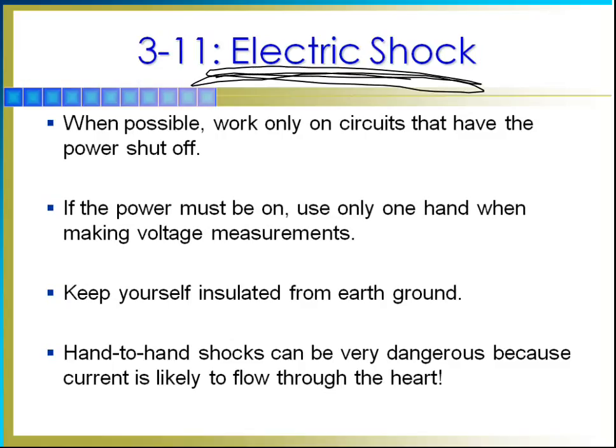Of course, removing rings, watches, jewelry, anything else that is conductive when you're working on a live circuit is a must. You should also, if you're going to reach in, make sure it's a cold system before you start hooking up your meter and all that. Once your meter's hooked up, you can turn the system back on. But if you got to work on a hot system, use only one hand. Put your other hand behind you, put it over your head, stick it in your belt.